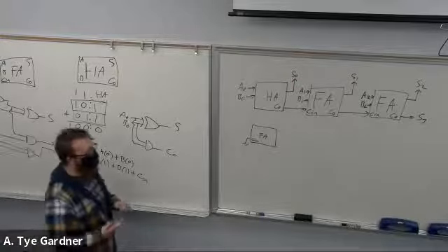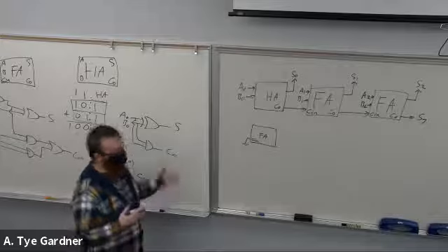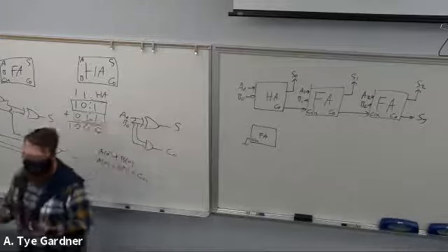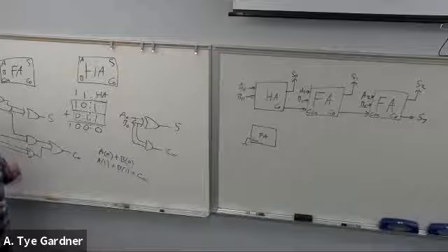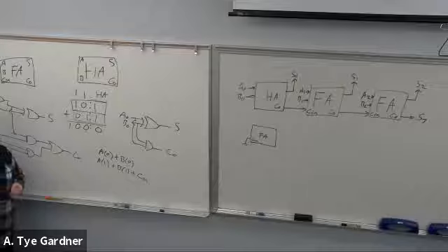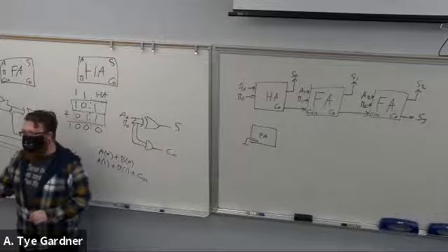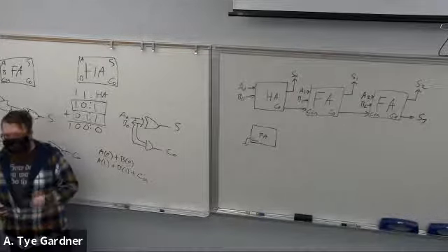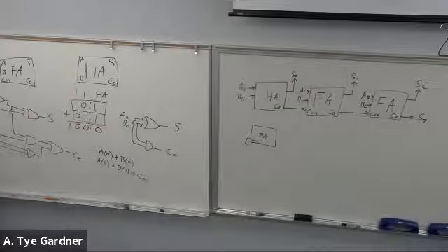What does it mean? Well, ripple carry means the carries ripple through the circuit. So on the exam, I had you guys draw a timing diagram, right, for one of the problems. That timing diagram doesn't have any of what we call gate delays. What that means is it takes some effort, some time to change from a 0 to a 1. So if we look at this, a simple but kind of bad way of doing gate delays is you would just in your technology estimate how long does it take for these to switch. And let's just say that every gate takes 10 nanoseconds. Now that's not really a good estimate because like an inverter is way faster than an XOR gate. Those are kind of extreme ends.